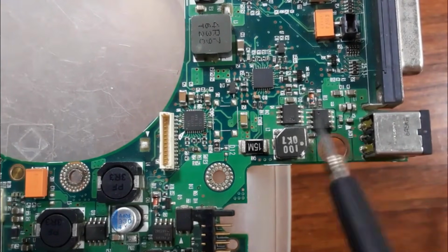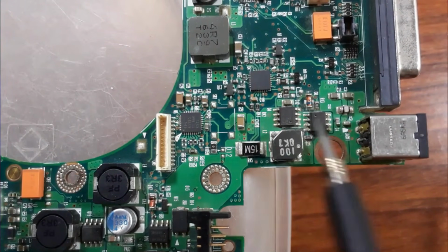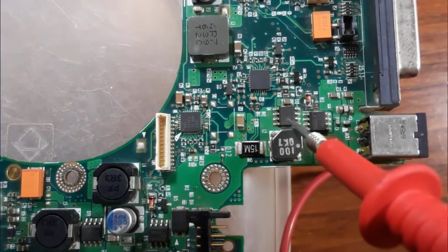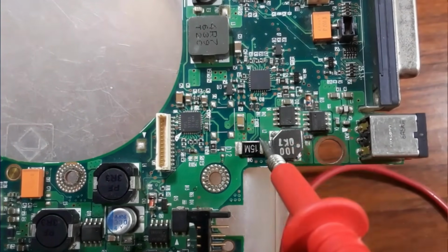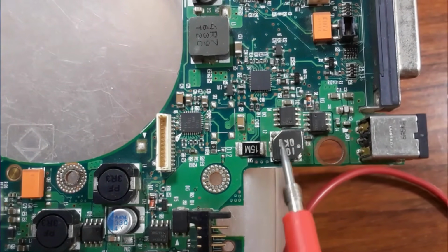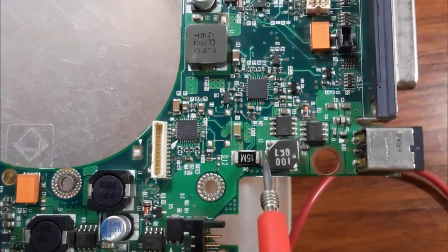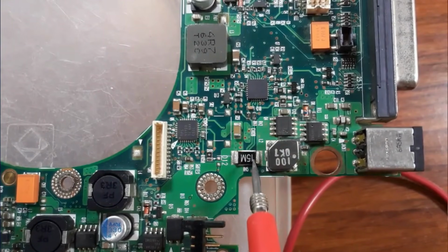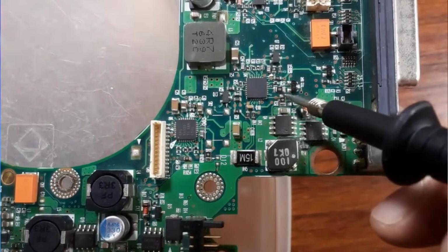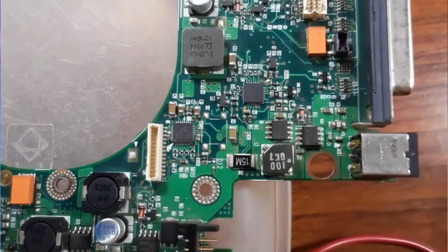After that, the other pins of this MOSFET, this MOSFET is the Q4. If we track the bus, we have the green color going directly to this resistance, this 15 ohm resistance, and also here we have the coil. This means that this MOSFET is connected to this resistance because we have the same color here. So let's check using the multimeter. If we put one probe here and check here, also the coil.